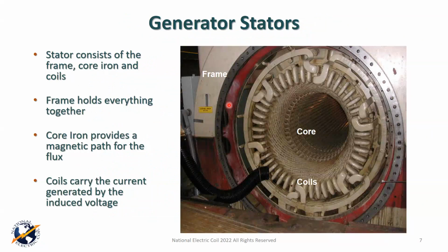All right, we're going to go through and talk specifically about the stator for a while, and we'll start with the primary components. It basically consists of a frame, the core iron, and the coils. And here's the frame out here. Some people call it all the gray iron. It has ribs inside here, sometimes posts that are round, to give it mechanical support, because the frame holds up the core and the core holds up the coil. So that's basically what's going on inside.